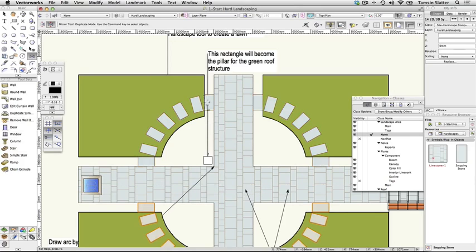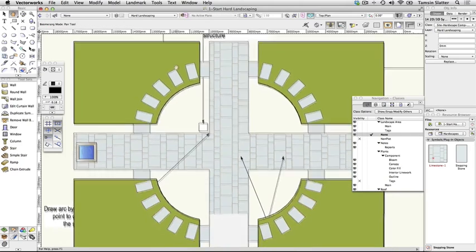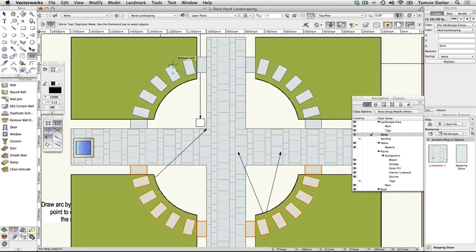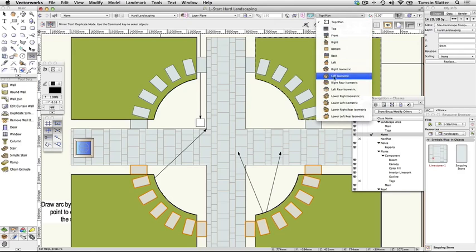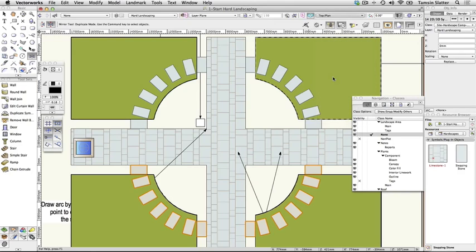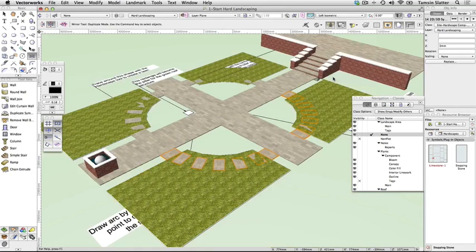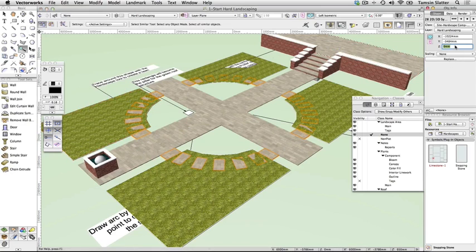The symbols have been placed on the Hard Landscaping layer, as have the lawn hardscapes. Both elements have a thickness of 35 mm. In a 3D view, their surfaces will be level, which makes it hard for Vectorworks to determine what to show. Using the View menu on the toolbar, choose Left Isometric. Use the Select Similar tool again to select all of the paving symbols. On the Object Info palette, change Z to 10 mm to set the pavers slightly above the lawn.